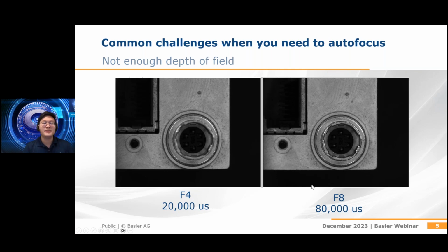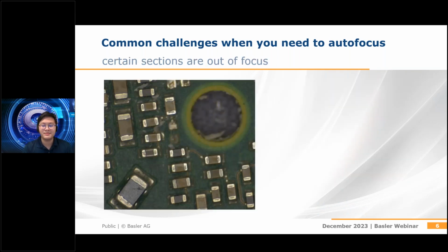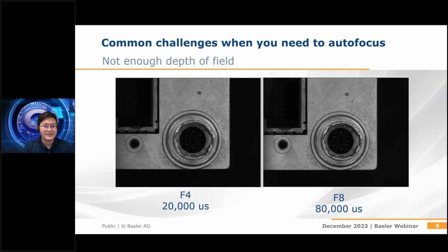Right. However, in the real-world application, when speed is very important, the exposure time cannot be too long. Because, for example, the vibrations from machines can cause the image to appear blurry or distorted. So, to get a clear image for such high-speed application, you will need to increase the aperture and then sacrifice the advantage of your depth of field.